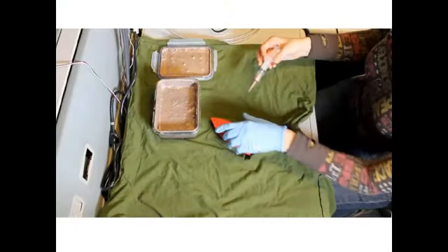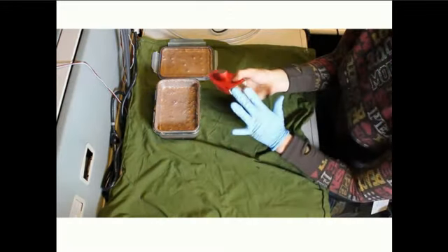In our case, instead of wires, what we create are hollow tubes. Once something is printed, you can take a syringe and fill all of those tubes with conductive epoxy, silver nanoparticle ink, any number of conductive materials that'll cure. So through one automatic step, you've created the geometry with all the cavities and tubes, and the second step is you fill it with conductive material.